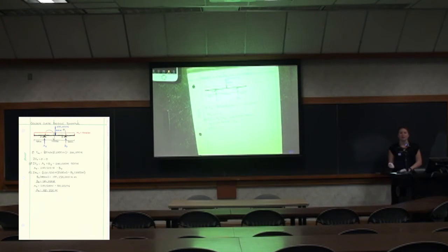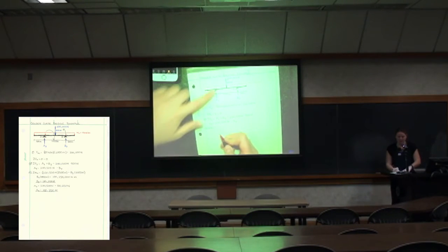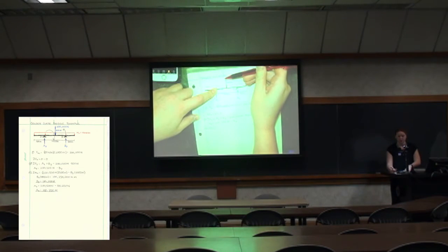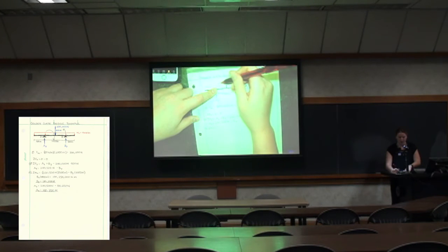So let's also set a positive sign convention of clockwise. So clockwise in this equation is positive. So at the moment A, we have the forces of the distributed load and the 500 Newton car that would turn the system in a clockwise rotation.